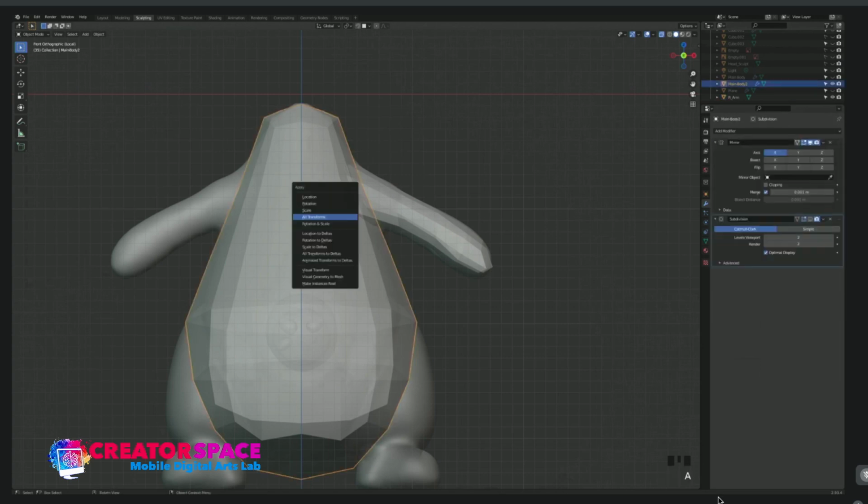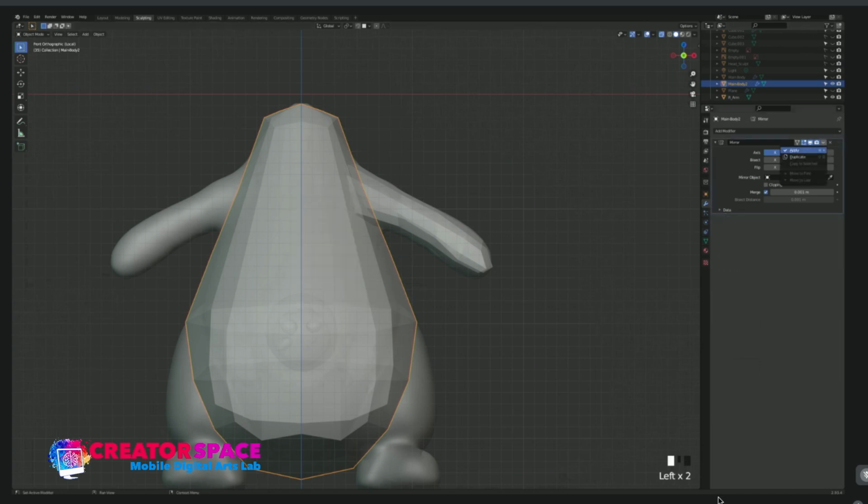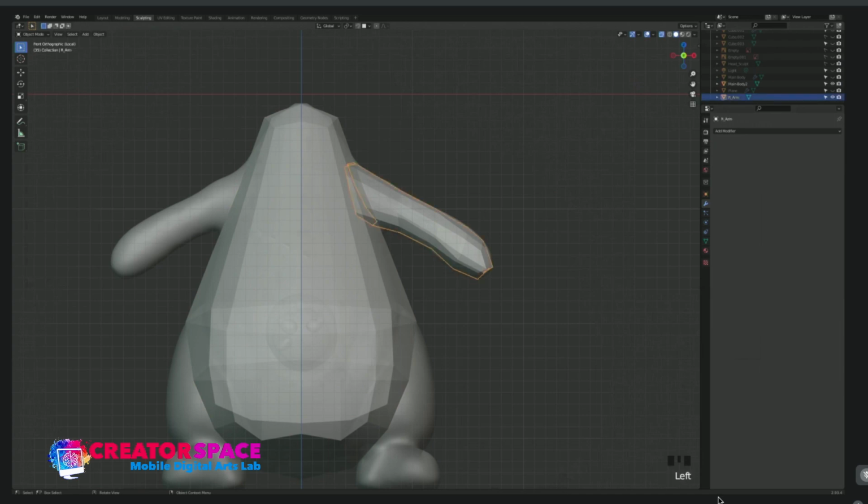So a visual transform to geometry. So just remove this. Now apply the mirror. Click in here. Add modifier, Boolean, union. Okay, and then you want to apply it. There you go. Okay, so let me go back there a little bit here. Sorry for the confusion. The order has always been very confusing sometimes for me.